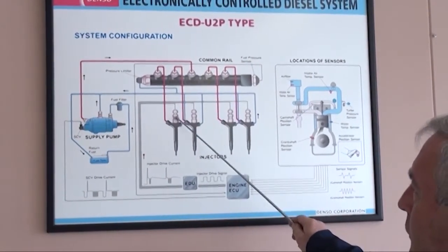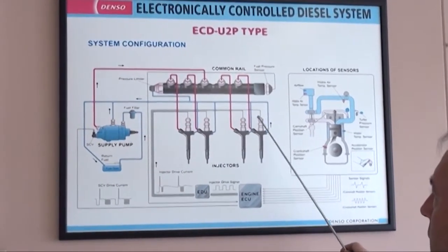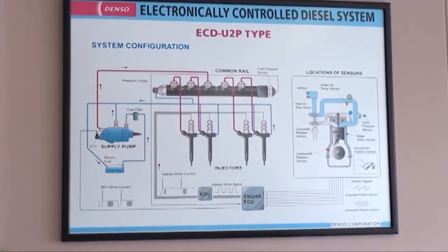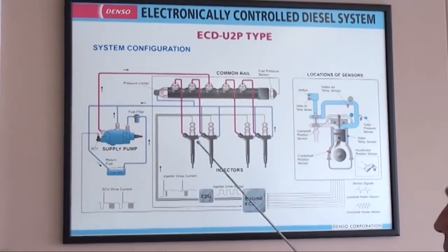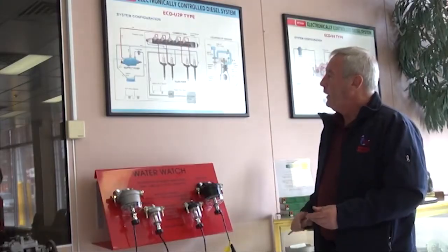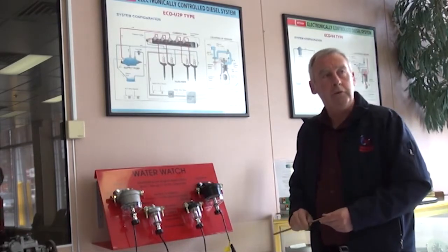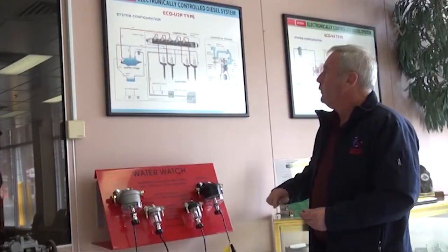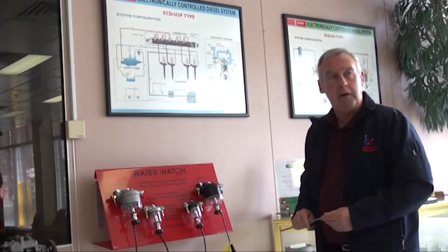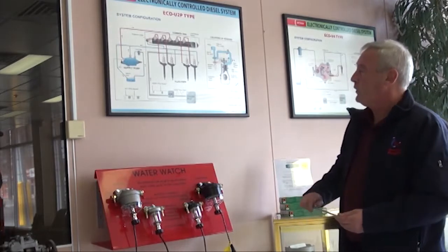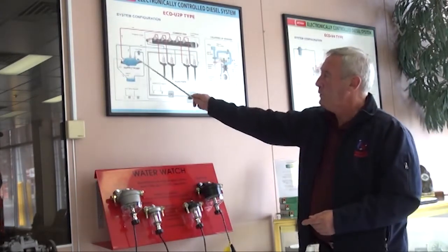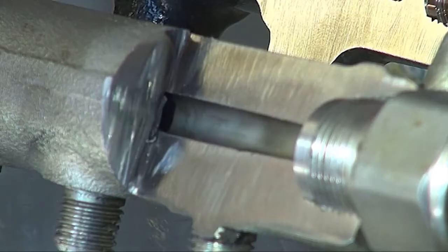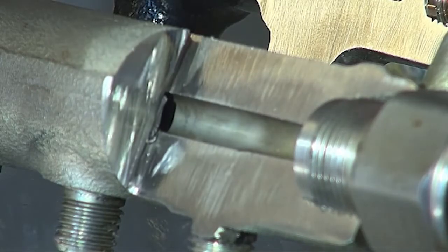The injectors are operated electronically with pulsing. It's a very high pressure system. It operates around 180 MPa or 30,000 pound in the old language. Makes for a vehicle with high performance, exceptional fuel economy, unless we get water in it. Water in common rail is very destructive. Damages the components, firstly our supply pump, the lines connecting to the rail itself, and ultimately the injectors.